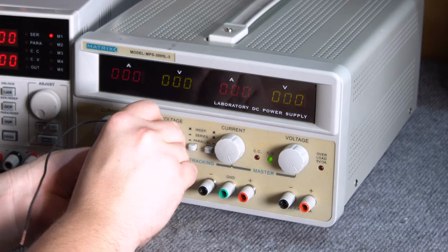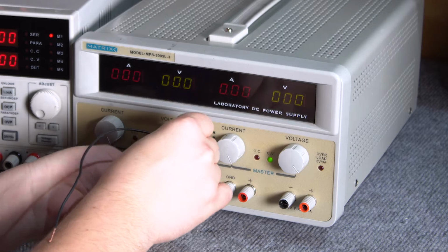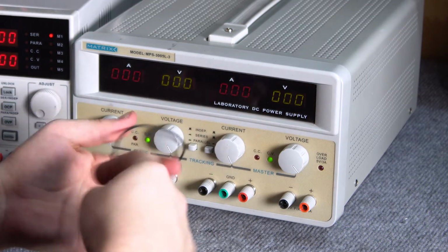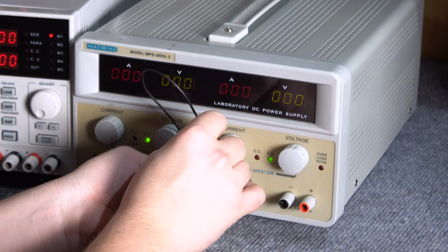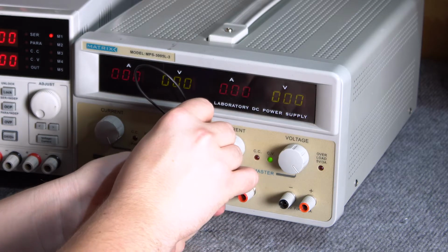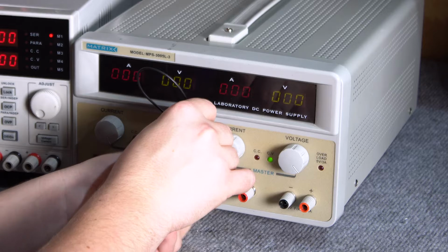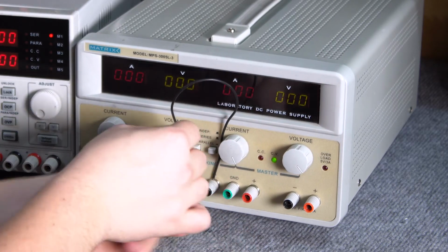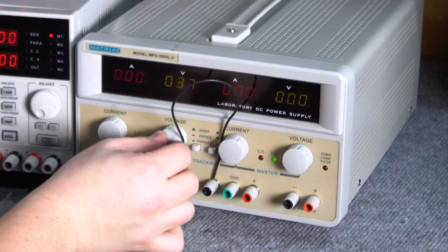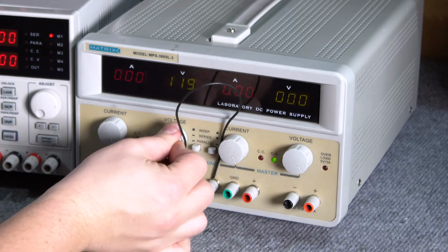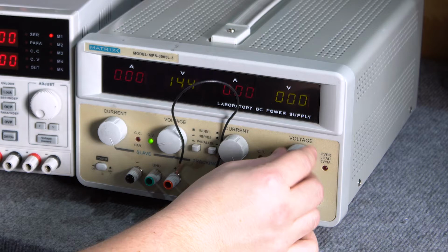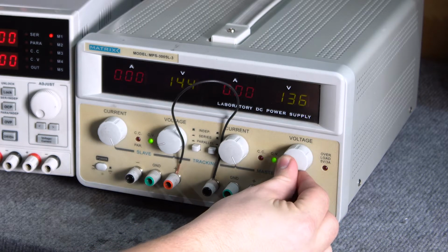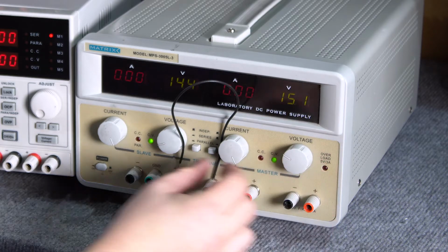We can also meet multi-channel power supplies. They can provide 2 different or the same voltages and currents. Some have the option of channel bridging. This means that we can connect the channels in series in order to increase the voltage or create symmetrical voltages, or in parallel when one channel has too low current capacity. It should be noted that the channels in the power supplies should be completely separated from each other.